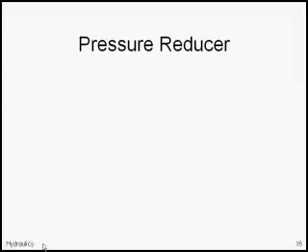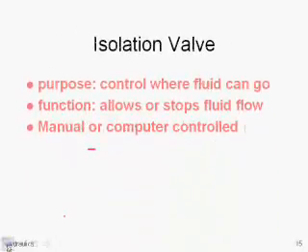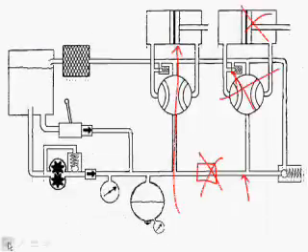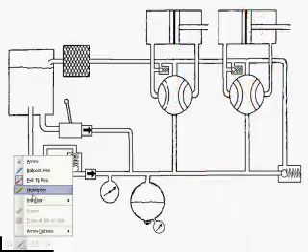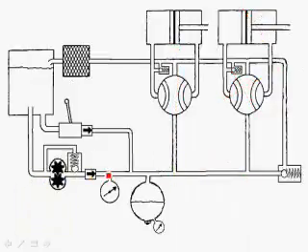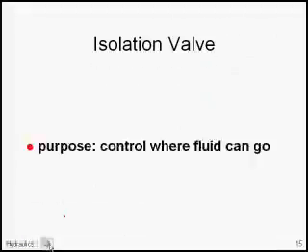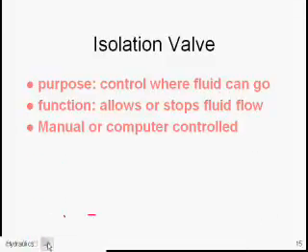And as I suggested before, whoops, I think I need to show you a picture. Not of the inside, but a diagram. Ta-da! Here would be a good place to put an isolation valve, right here. Now you could isolate the pump from the rest of the system. You could also put an isolation valve right here. You could rotate it and let fluid go through, or you could rotate it back and turn it off. So when you get in those transport category jets, big biz jets, big turboprops, you're going to be seeing that there are some isolation valves in the system.